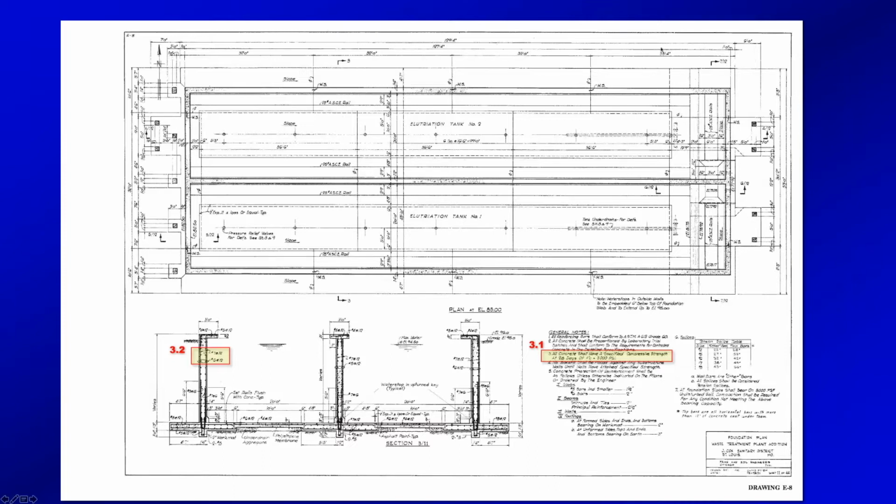Well, okay, so you have an overall length. You're talking about like 109 to 129 foot 4 inches. Is that what you mean? Is that what that says? 129 and 4 inches. Okay. It could be 189, but I think it's 129 because the one below it looks like 127. So that would make sense. It's 129 to here minus, they're coming down on the right-hand side, down and over a foot. So that makes this 127.4 because they're taking a foot off of here and a foot off of here.